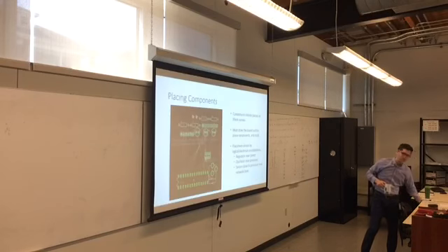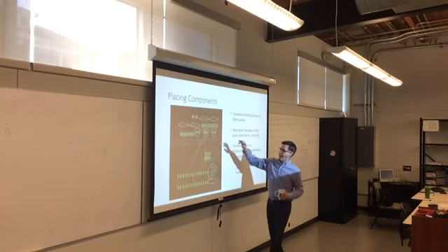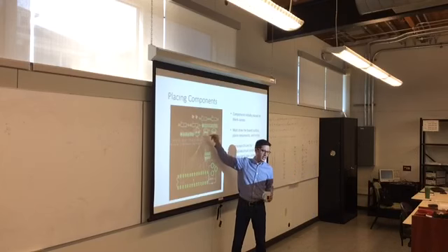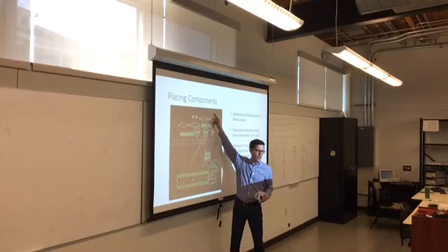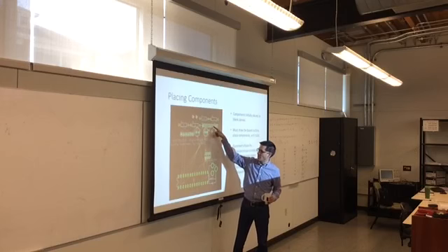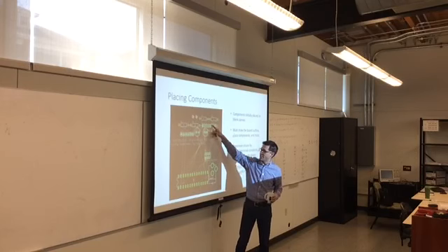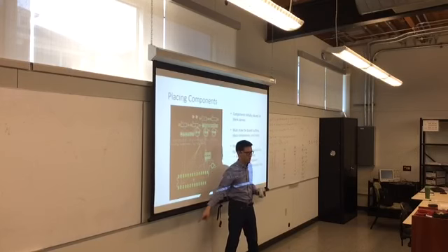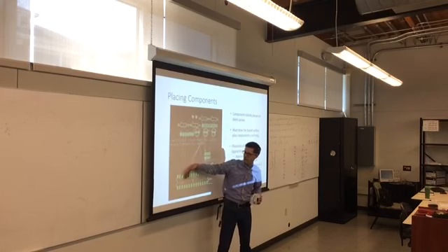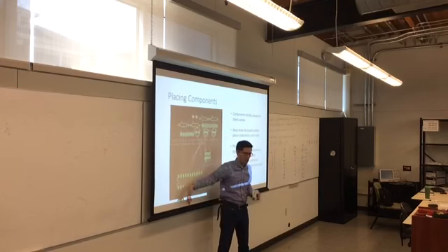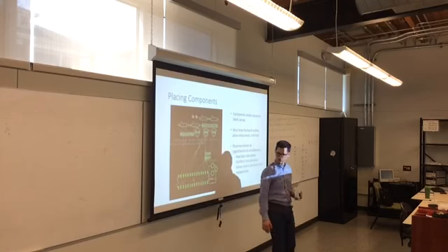If in the layout, it really doesn't make any sense to have this device with so many connections strung out all the way here past all these components. At the same time, it also does not make any sense to have this header on the other side of the board because all of these nets would have to get routed underneath the chip and through all these holes.